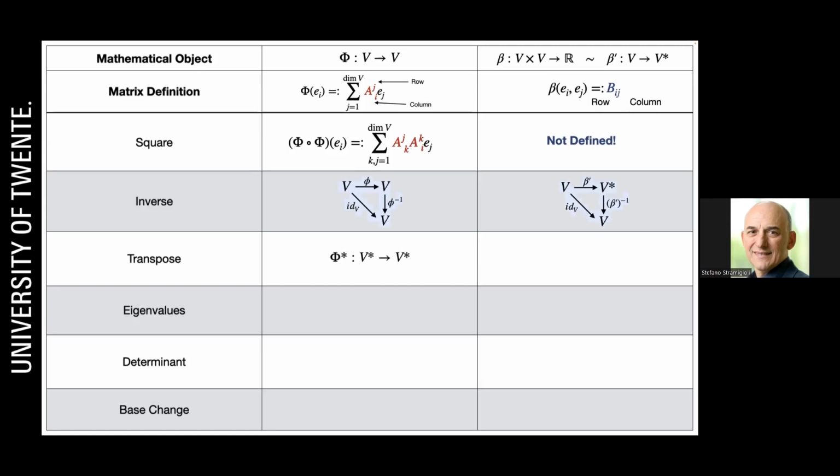The transpose is what is called the adjoint map, which is used all the time. It's the transpose Jacobian. So when you go from coordinate space, velocity in joints, to velocity in workspace, that's a map. That's actually called the push forward on the nonlinear kinematic map. And then you have the pull back, which goes backward, and it does not map velocities, it maps forces. It's the same thing. Tensorially, the Jacobian transpose is the same thing, you just use it differently.